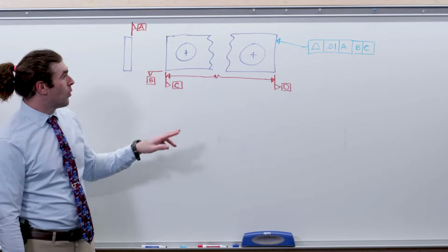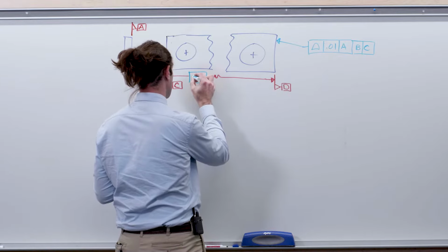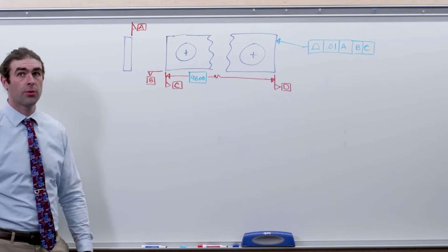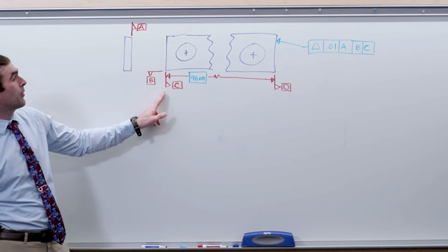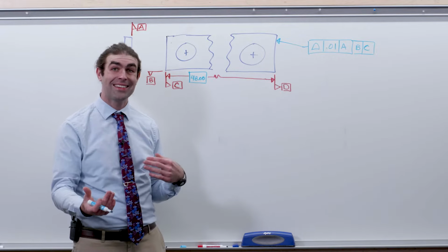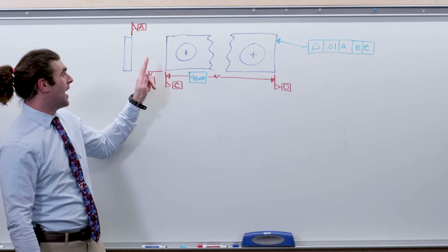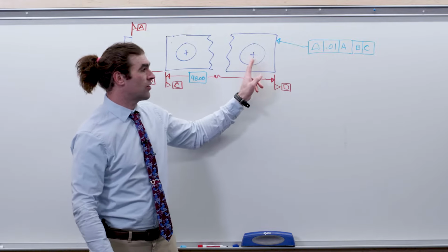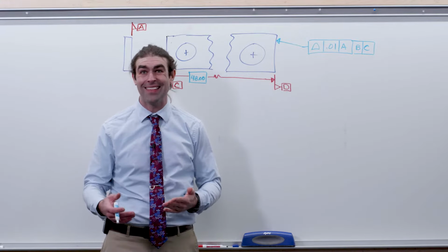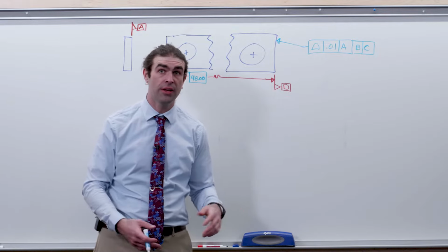Now, we're going to use a basic dimension here. Say it's 48 inches, okay? So we're going from datum C to datum D, the overall length of the part. The idea is we would want to have a position for this hole to A, B, and C, and the position for this hole to A, B, and D, to make it slightly easier to inspect and functional enough.